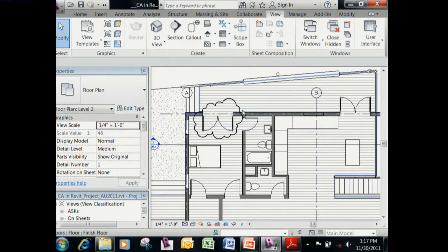One thing I'll talk about briefly is that, just like there probably has been for years, discussion, sometimes heated discussion, about whether to cloud in model space or paper space in CAD, there's the same issue in Revit, whether you want to cloud inside the views or inside the sheets. I think there's a pretty good argument for clouding primarily in the views, in that if you have a revision and you cloud it and then you tag it, and then you have a future revision, you want those previous revisions to show up in what you're issuing.